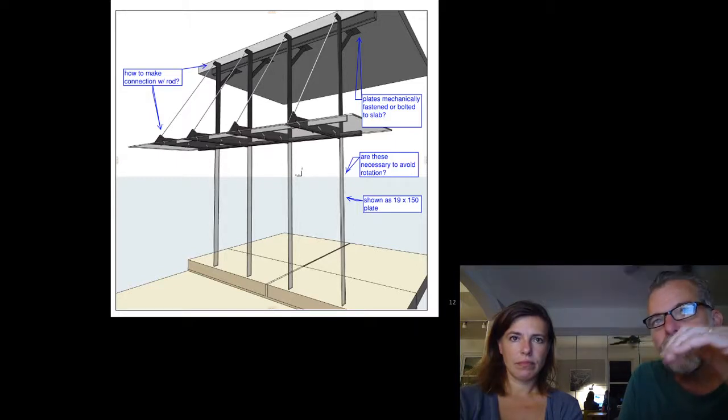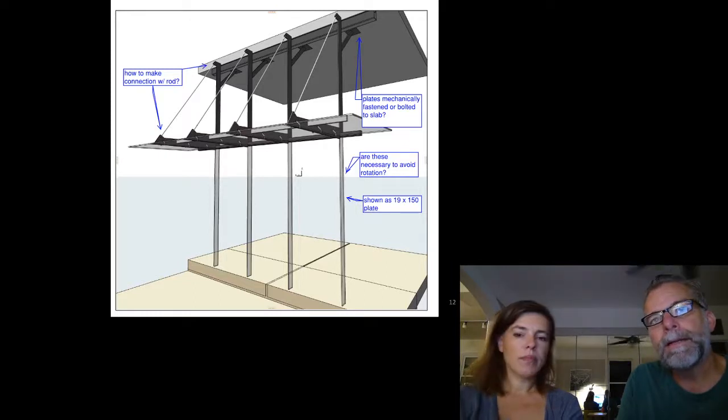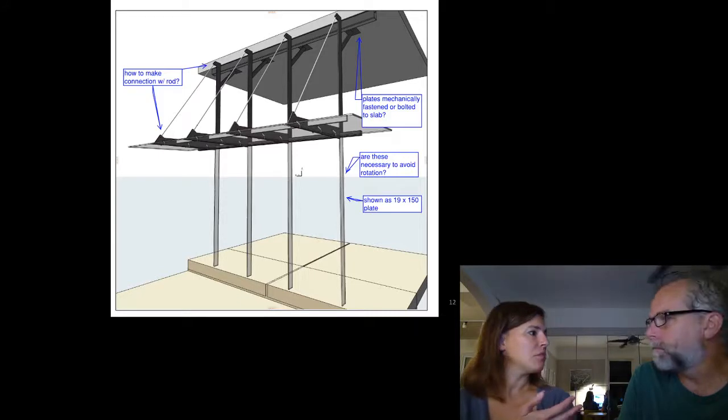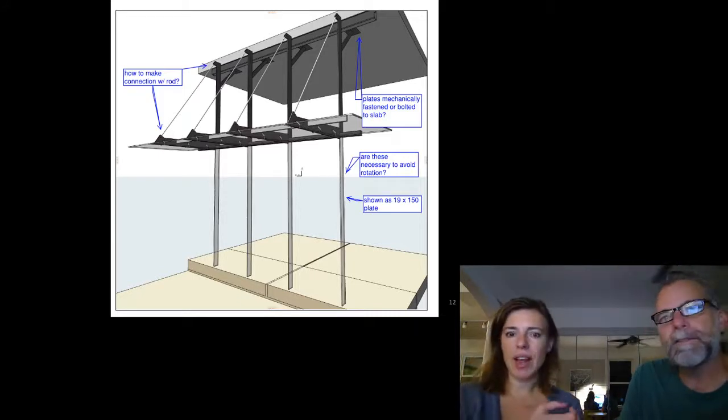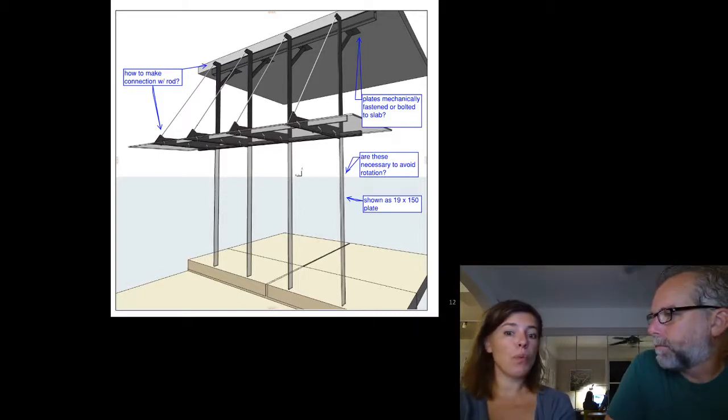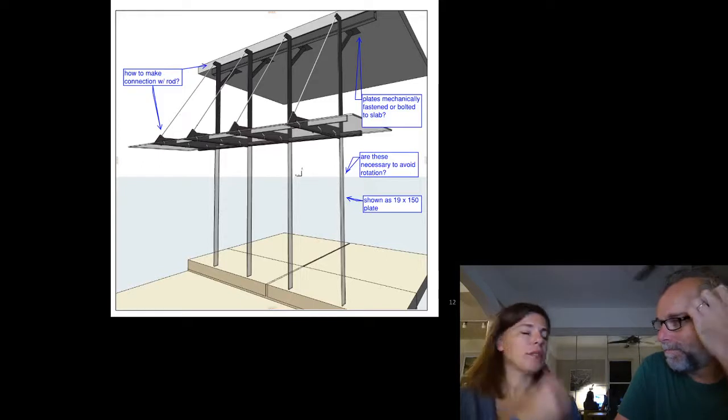So it works for both the downward snow load and the upward wind load. But we're talking about probably, so instead of a 19 diameter rod for tension only, we're probably talking about 3-inch. Yeah, that's probably what I was thinking. 2.5, 3-inch HSS or round pipe. So visibly, what kind of just disappears from your eye starts to be really noticeable.